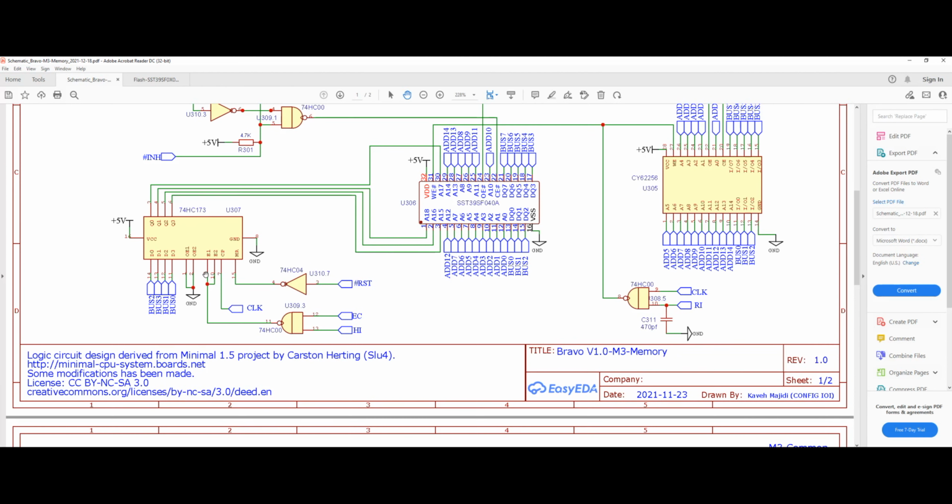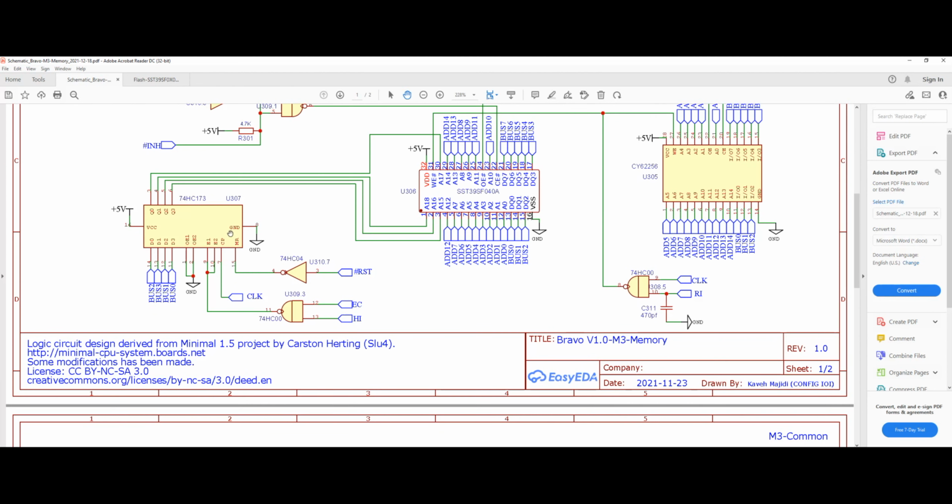However, on the input side, again, we have two pins, pin number 9 and 10, that you can see are tied together and controlled by a control signal. This is again an active low signal, and whenever we want to read something from the bus, we just need to bring both of these lines, E1 and E2, low, so that we read the value from the bus and put it into our register. Other than that, we have a clock pulse signal that comes to pin 7, and whenever we want to read something from the bus, we need to pulse the clock.